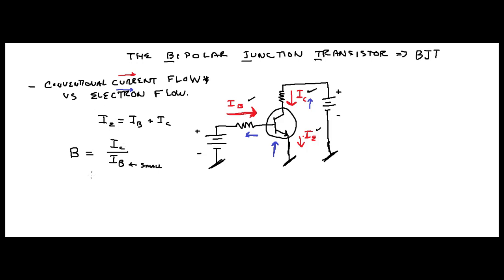So depending on the transistor that you're using, beta, by the way, I usually draw with a little tail here, beta can equal, depending on the transistor, 50 to 200. I mean, it all depends on the transistor. Here is your amplification, all right? A small current going in your base can produce a large amount of current flowing in your collector and your emitter, all right? That's very important.